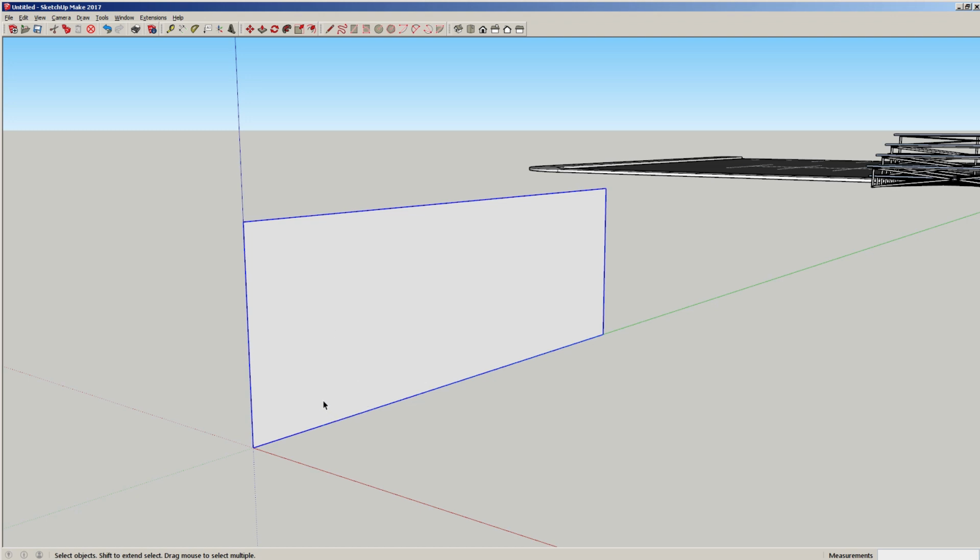Now when you're building in feet, it's also called decimal. And in decimal, you can build in certain increments, like 0.5 is 6 inches. For steps, typically they're about 8 inches, which is like the height of a block. So we're going to start at this corner origin, and go up following this vertical blue axis. Don't click yet. We're going to type in 0.67. You can see it down on the right side. Enter. So there's our 8-inch block. It's typically what you want.